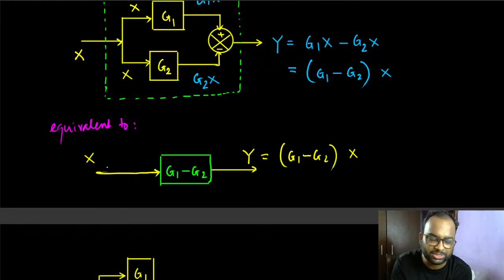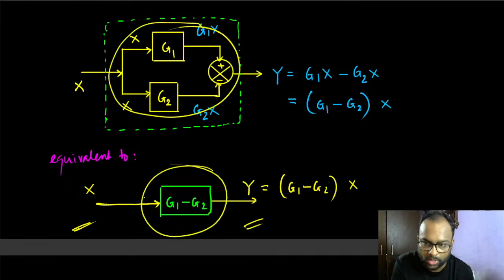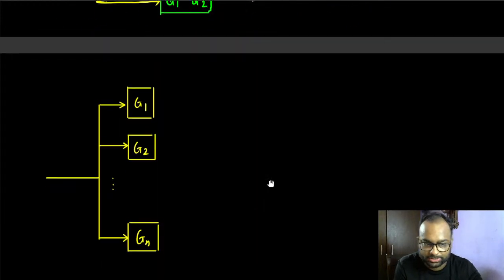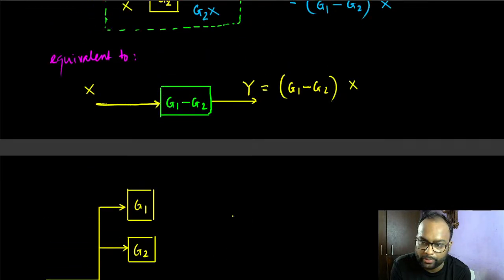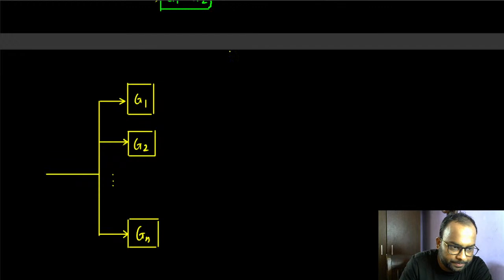This is again by convention. The idea is that if you don't have a 2 kilo ohm resistor, you can just put two 1 kilo ohm resistors in series and put them in the circuit, and the circuit will never know. As far as the input and the output are concerned, they never know whether this was the circuit or this is just the circuit. That's the idea here. So in the black box model, we actually get rid of all the internal complications. I think I answered your question. Again, if you are not satisfied with the answer, you can once again ask me.